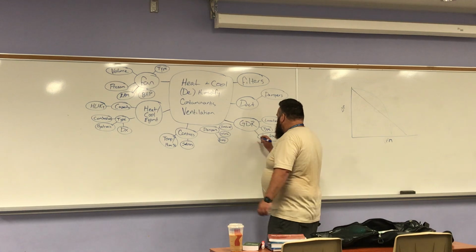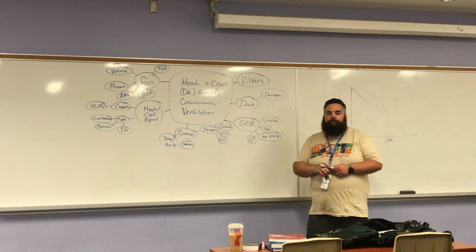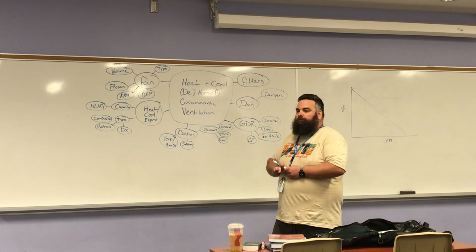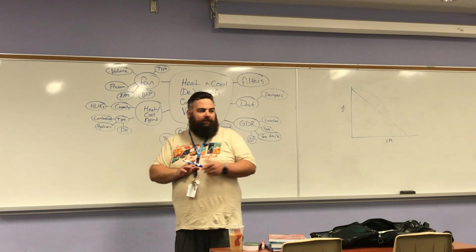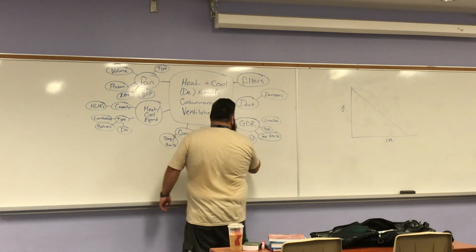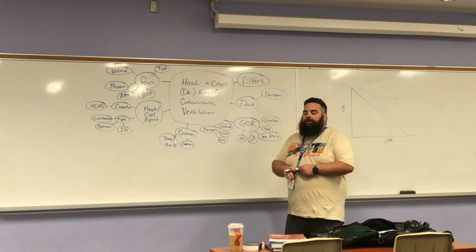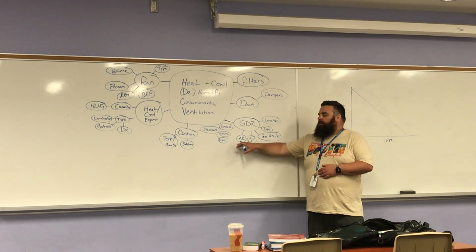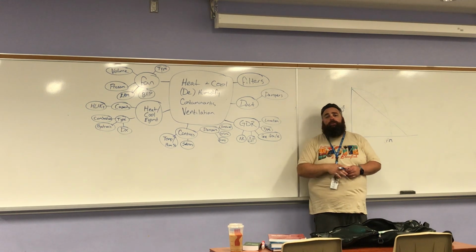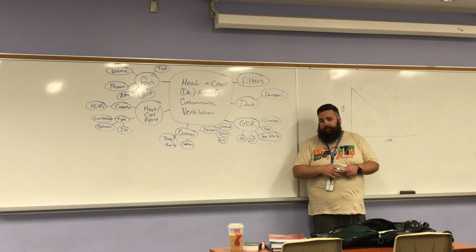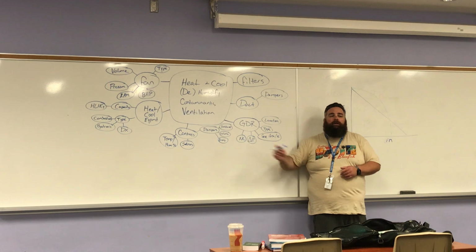Pressure drop. Yep, delta P, very important. What else? Do you guys hear anything from those diffusers right now? Sound. It's a good thing. Sound, right? So we're gonna call that NC, noise criteria. We can select our diffusers based on either velocity for sound, where we'll say we can't exceed 1,200 feet per minute through that diffuser, or we'll look at the published NC ratings on the diffuser and get that.